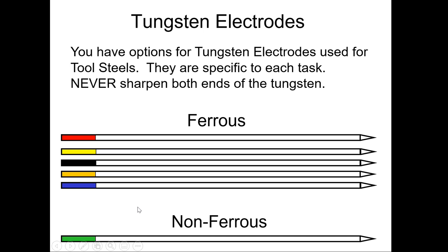I'm going to make this point right now, and I'll make it as clean as I can. I've worked in many shops and worked in a lot of different places, and everywhere I go, I take lanthanated black, and I replace everything in the shop with just lanthanated, because I can and have proved that I can do absolutely everything with a black lanthanated tungsten. I could use it on AC, on a conventional machine, where I can put a nice little ball on the end of it like I want. I could use it on AC with an inverter that requires higher frequencies, and I could use it to weld aluminum as well as with a 2% thoriated.